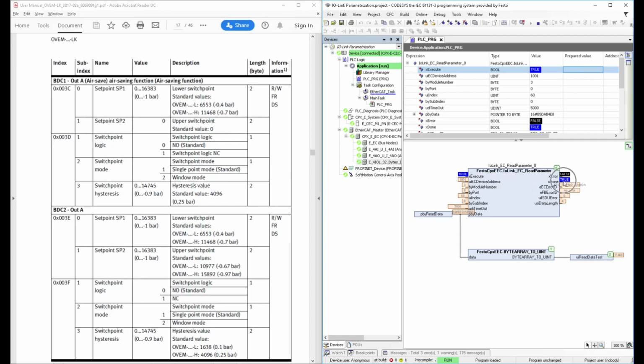And by the way, I'm getting a done bit here. So that's what you can use for handshaking whenever you put this into a sequence. So now I can say, okay, done. I can make this false and I can keep moving, right?